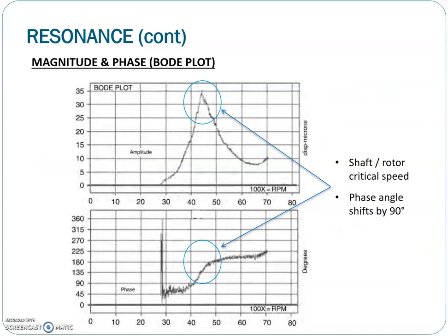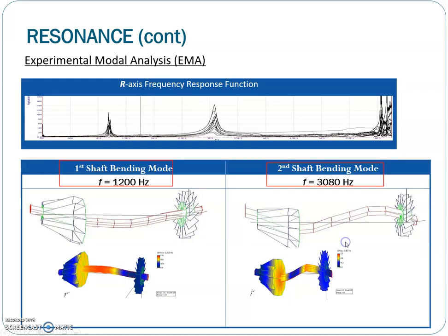A Bode plot can help to identify the resonance speed or resonant frequency of a rotor, or examine the rotor dynamics on an order basis. Modal analysis is a complete dynamic behavior test which can fully determine the dynamic characteristics, namely the natural frequency, damping, and mode shapes.